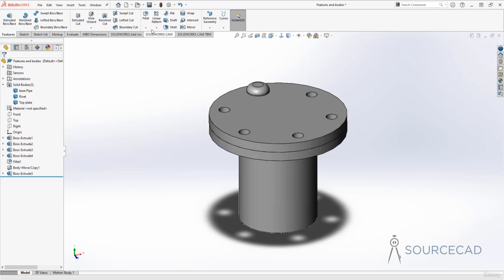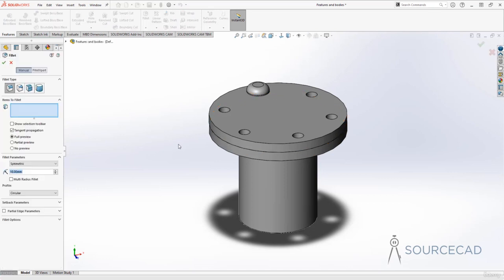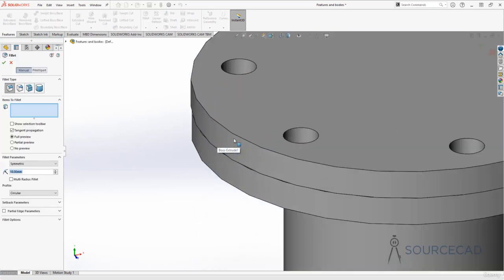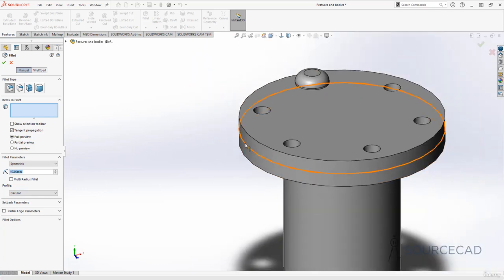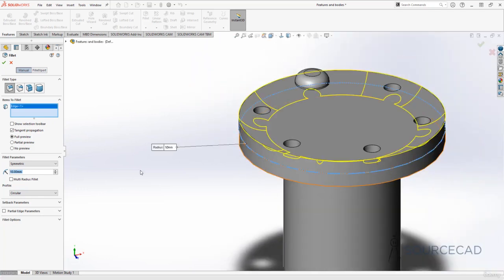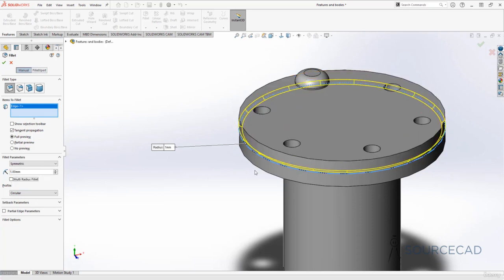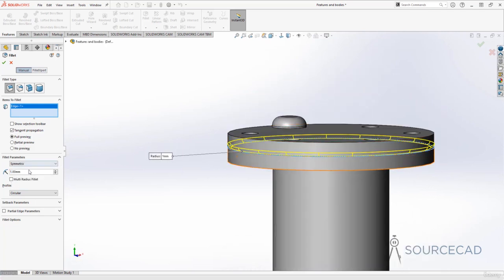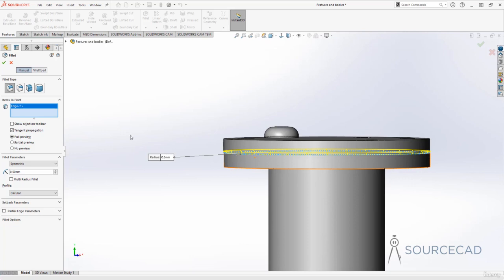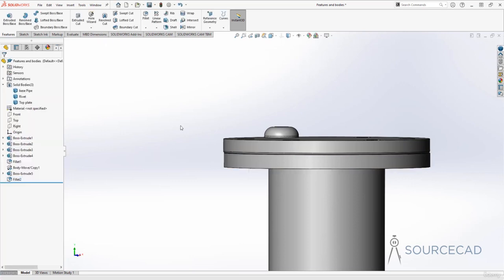fillet here. So I'll go to fillet, and I'll now start with this top plate. So I'll just add a small fillet right here, and well, that's huge. So let's just change the radius to 1 unit. There we are. So we've got this small fillet. Maybe let's just use a radius of 0.5 and tab key. So this is what we are getting now, a small fillet. Click OK, and there we are.